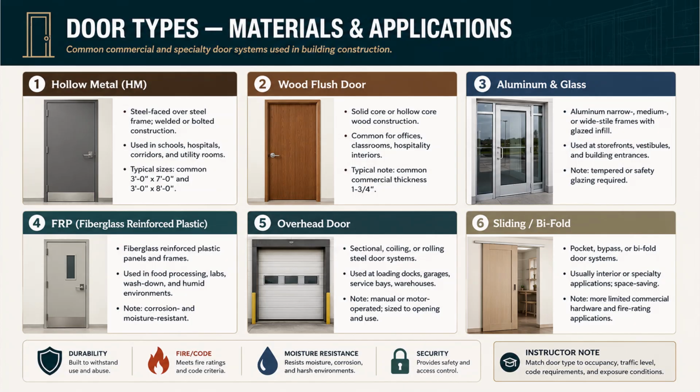Durability, fire and code, moisture resistance, and security are the four lenses you select through. And the instructor note is the rule for the whole slide. Match the door type to the occupancy, the traffic level, the code requirements, and the exposure conditions.